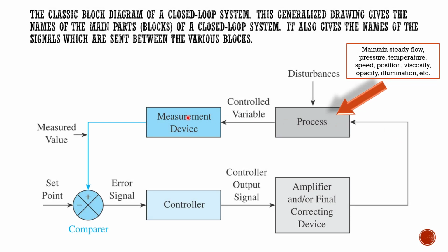Here's the feedback loop here that's a little clearer. I've got my set point and I've got my comparator, because this is circuitry. My set point in this case is probably coming from, let's just say, a dial on my operator station, and when I change that dial, it's moving a potentiometer that gives me a voltage that represents where I've got the dial set.